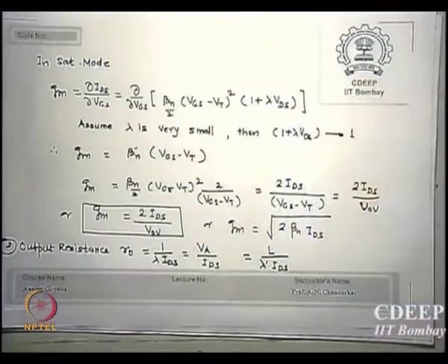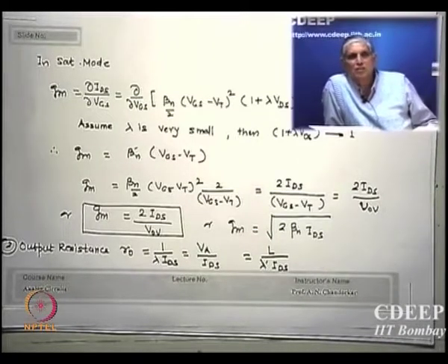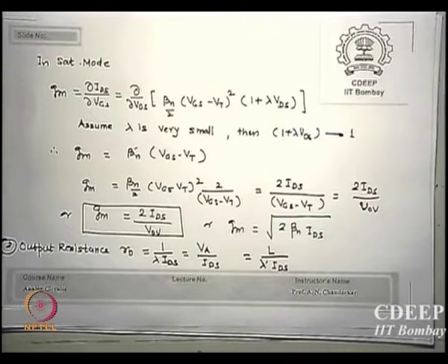The interest for us is in analog circuits, where we said MOS transistors are always maintained in saturation. What is the condition on VGS and VDS in DC when the device is in saturation? VGS minus VT should be smaller than VDS at any point. Every time VDS should exceed VGS minus VT.